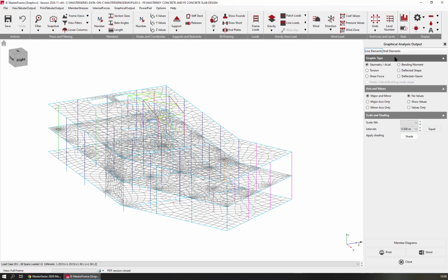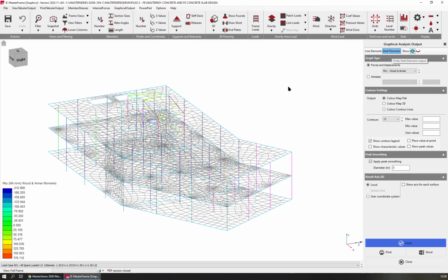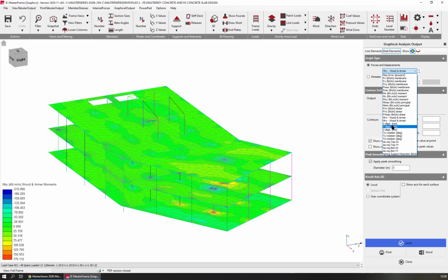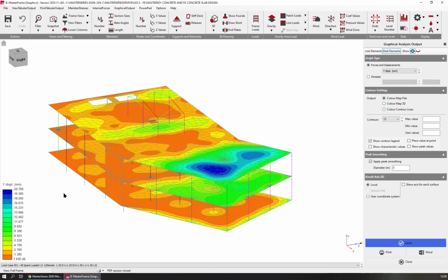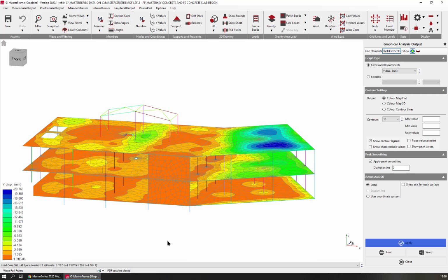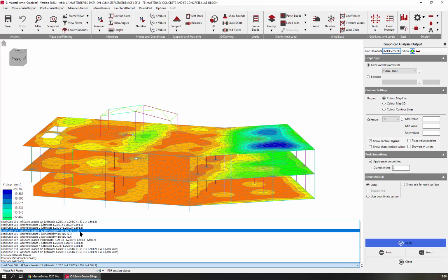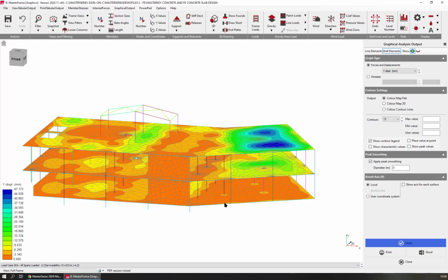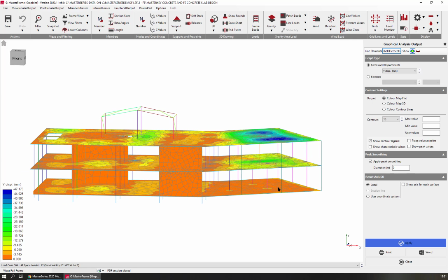And if we look at the shell elements and we look at the Y displacements, we will see that the Y displacements under all span service, this is all coming down considerably, and it's to be expected, and this is moving down further more than this because of the, I'm trying to think of the right word, the spring stiffness of the soil.